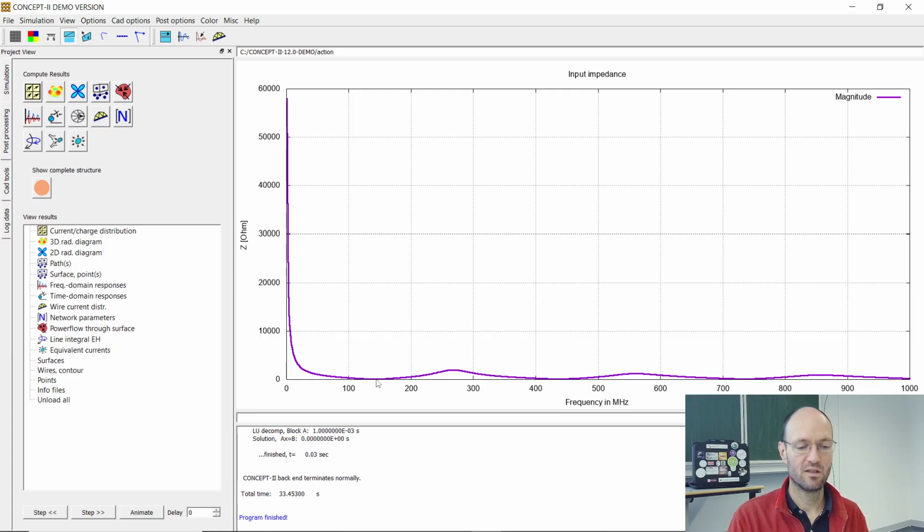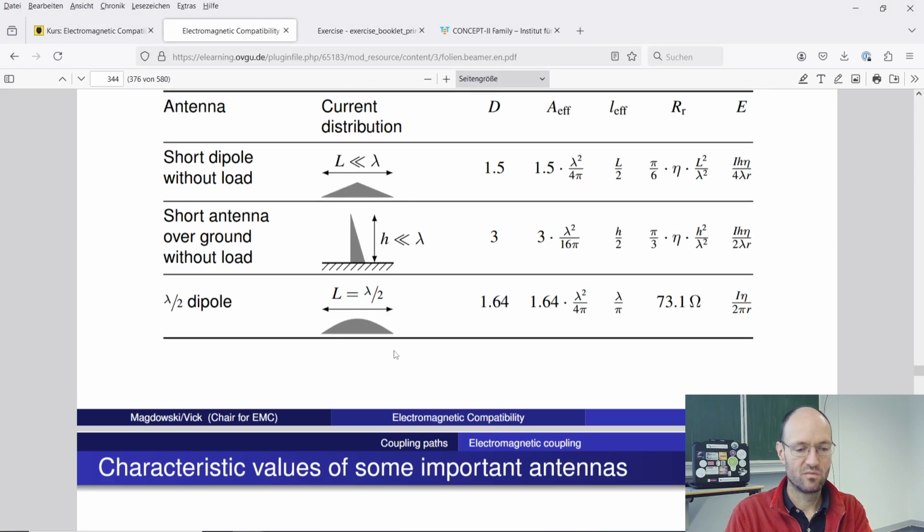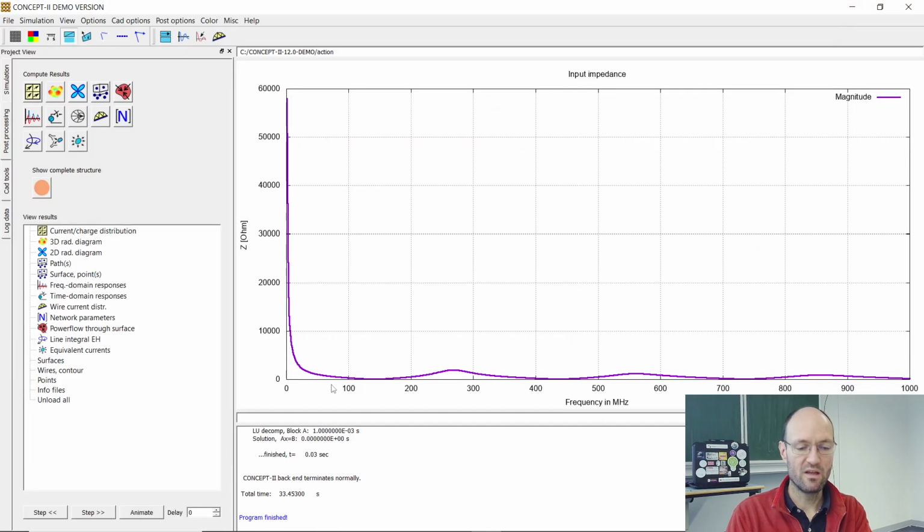And there, the input impedance or the dipole is well matched. This is when we had this current distribution. So here input impedance gets small, and you can also see that the radiation resistance also has a certain value here, some kind of fixed value. Okay, and so then if we go up in frequency, we get another maximum. This is at around, shortly before 300 megahertz, and then it goes down again at 450 something. And so these are these frequencies that we also checked before.